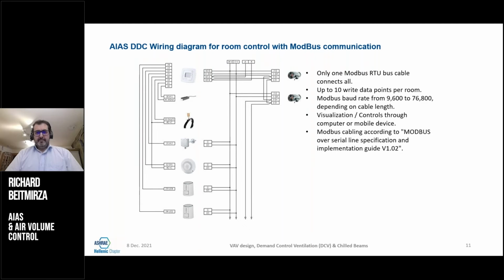So if it is used with chill beams, you can control the water. If you're using chill beams, you can control the condensation sensor to make sure before you have any humidity or if you have any condensation, the valves get shut down automatically. You can control the air volume that goes into the room. So all this demand control ventilation is going to, let's say, the next step to be able to maintain a very good mix between different ratios.